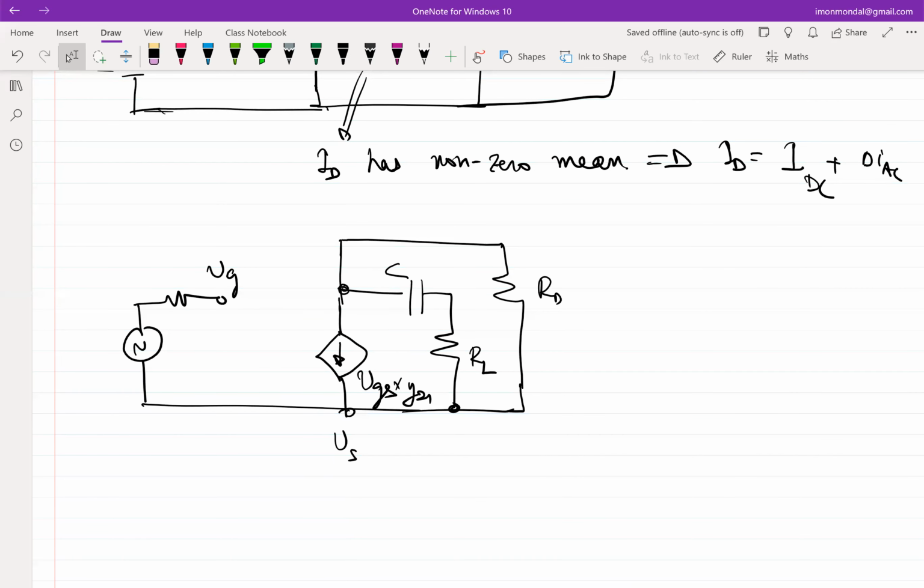So what I'm interested in figuring out is whether there is a constraint on the capacitor such that the capacitor behaves like a short circuit at the signal frequency, assuming that signal frequency is not DC. Obviously, it's not DC, otherwise in the incremental model there's no point in putting a capacitor. A DC capacitor would have been open. Yeah, C must be very large. Now, C must be very large with respect to what? Infinity is obviously a solution, but when you are designing a practical circuit, you cannot hope to put an infinite capacitor. I need to figure out what is the limit, what is the constraint on C.